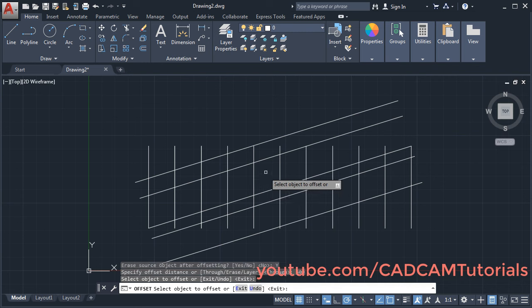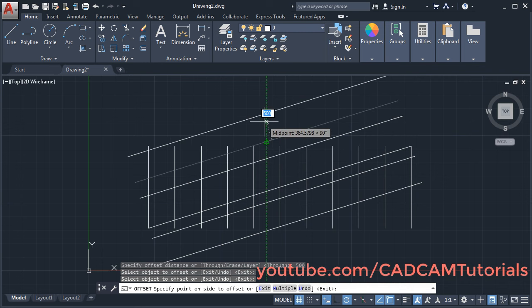Then select object to offset. I want to offset this object. Then give the direction where you want to offset and click. So here you will see that the original line got erased and only the offset line has been kept. Then press enter to stop the offset command.